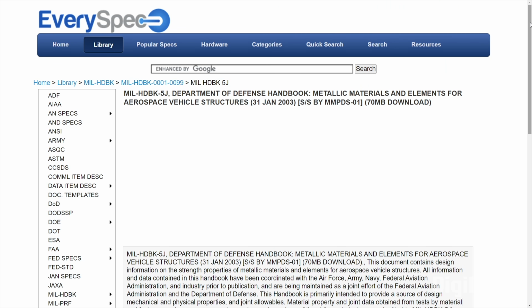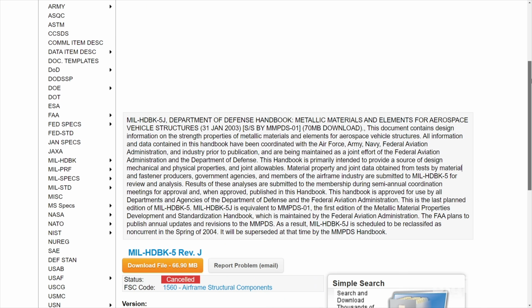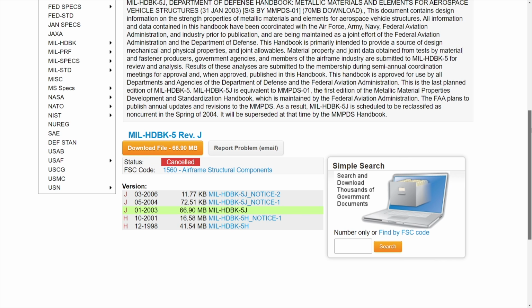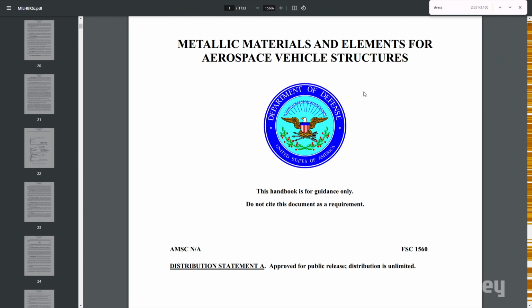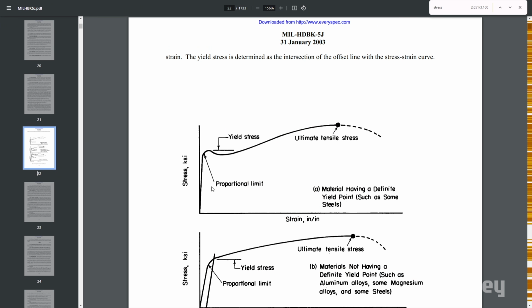If you are designing important mechanical components, like for aircraft, then you'll want to dive deeper into stress analysis and use something like the Mil Handbook 5 to see what loads various materials can handle. I won't get into this here though. I don't have a particular challenge for you, but maybe just play around with the FEM Workbench. See if you can reduce the displacement and stress even more by, say, making the bracket wider or longer to accommodate another mounting hole.